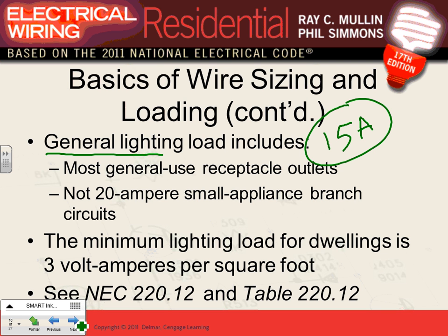If you ask me personally, I would say it's overkill. I know some people do it. You're going to see a 20 amp branch circuit in a dwelling needed in certain applications. In all other applications, a 15 amp circuit with number 14 wire is good enough for you, no question asked.